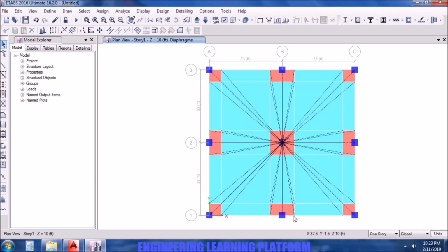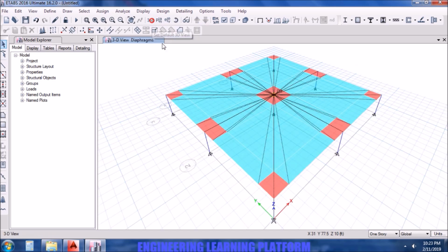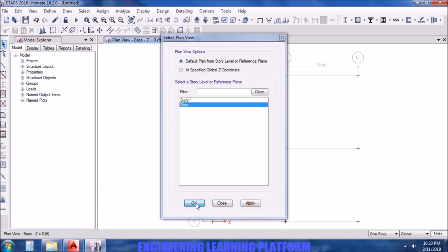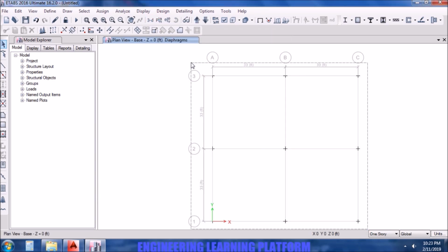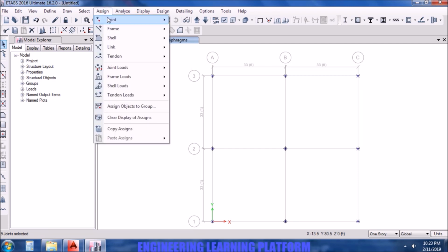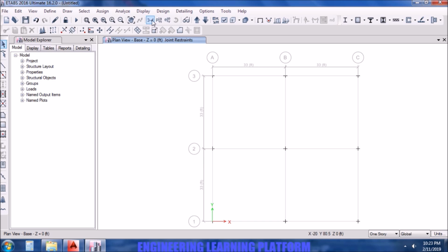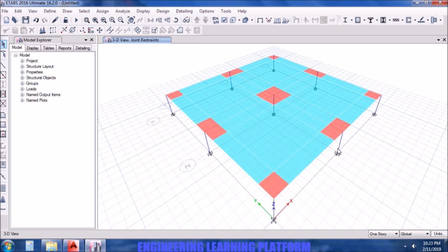It is basically important in case of earthquake loading. For the design of the slab, usually we don't consider earthquake loading since it's governed by gravity, as the stiffness of the slab is high in the earthquake loading case. So making the column support fixed at the bottom.